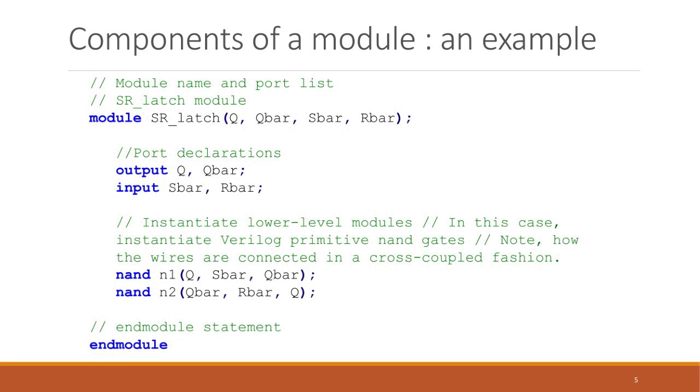But it is not the case here. That is an important thing that you should notice. You should strictly note that this is not equivalent to function calling in any way. This is only about creating an instance of a circuit module definition and placing it in our design.